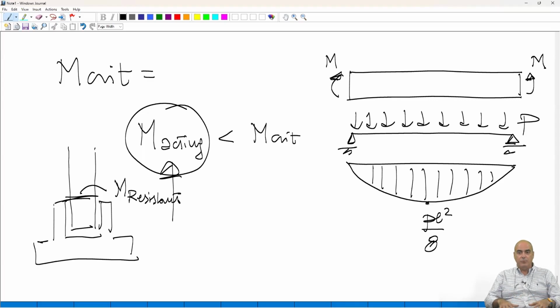This acceleration of the ground is transferred to the structure, and the structure has its own vibration characteristics, so it can modify this acceleration. And it ends up that the masses of the structure vibrate with an acceleration. So that mass with that acceleration is the inertia effect that we consider as the force equivalent to the earthquake. But the stiffer is the structure, the worse is the case, because the stiffer is the structure, it means that you pick up the acceleration of the ground and you do not modify it.